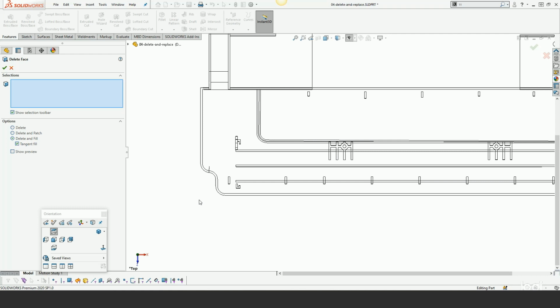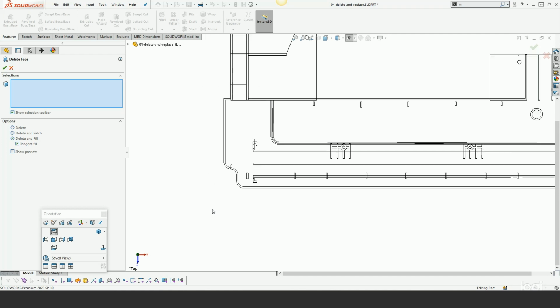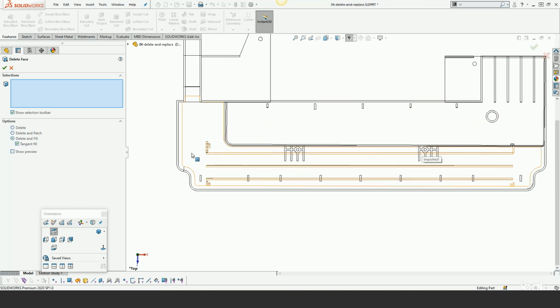And then the other crucial key is I go from box selection to lasso. With lasso, it allows me to do some very specific selection to be able to remove a lot of geometry at once, and I'll show you how. It might also make sense to use the filters. So I'm going to use the face filter, and by starting here outside the model and lassoing carefully around these areas, we're going to remove all of this geometry at once.